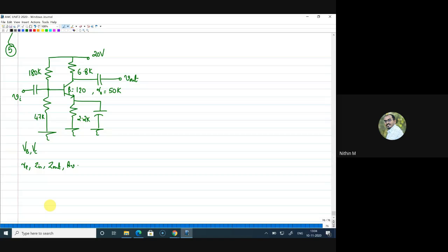Now, can you tell me what type of amplifier this is? It is like source degeneration. Okay, so you said it is degeneration because you have seen a resistance at the emitter terminal, right? So the very first thing is to check where the input is given. Input is given to the base, and output is taken from the collector. So this should be a type of common emitter configuration. It can be a common emitter amplifier or a common emitter with degeneration. Yes, sir. Since the capacitor is present, we will see what modification will happen. We will deal with that soon after doing the DC analysis. So I'll write CE for now. We will see whether it is common emitter with degeneration or a simple common emitter.